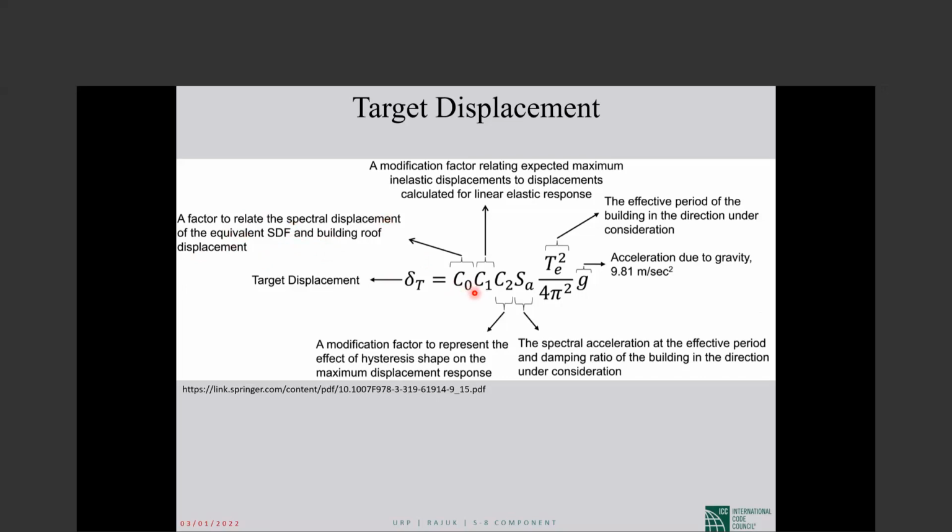We also had it in table form depending on the building. But I forgot to say how we recognize whether a building is shear type or bending type. We apply a lateral load to the building and look at the story drifts.